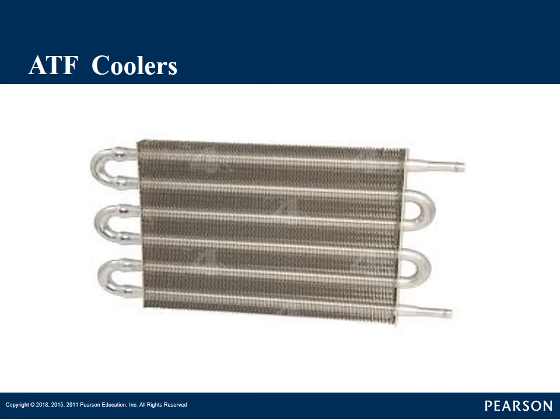Okay? Your better tube coolers have what they call turbulators in there. Basically restrictions that cause that fluid to change direction and mix. Because if we didn't have those at all, you would just have fluid running through this big tube.